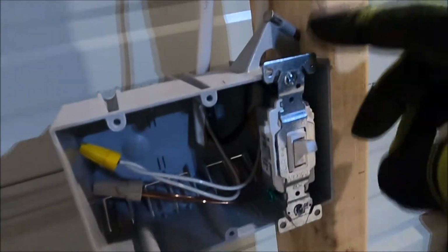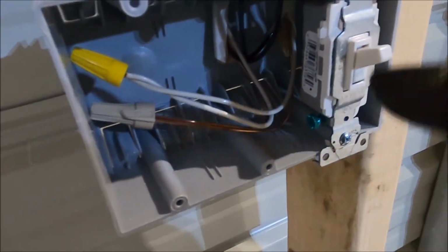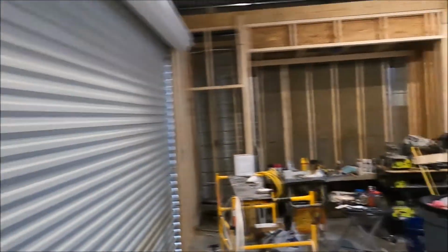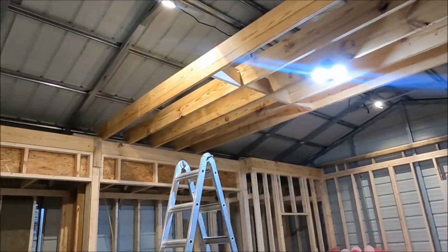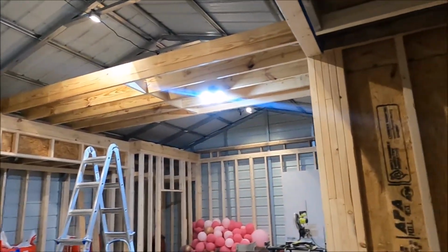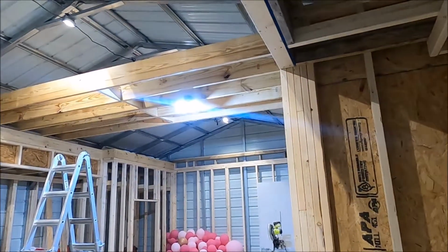Okay, I don't have all the boxes in place, but I have enough to do some damage. So we're going to start out at our panel box. What I've already done is I've ran the hot wire up to make this box hot. This power comes in, goes to the switch, and then I have a piece of Romex that goes up and over and then to this light. Out of necessity, I just threw this one light in, and it's actually where that box will eventually go when all the joists are in.